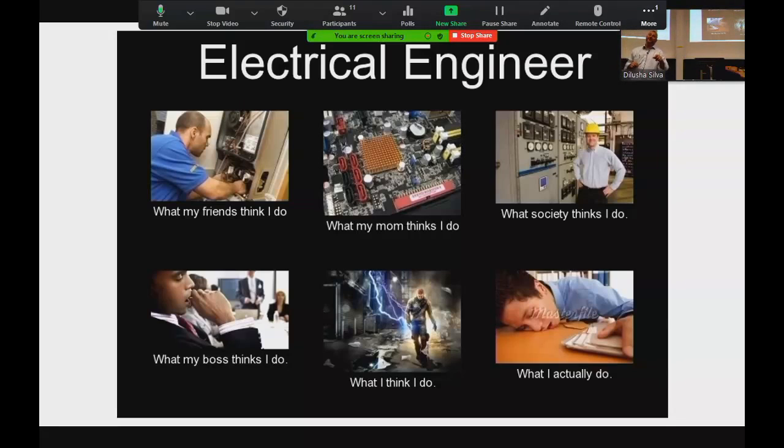Within this sort of application, for the load you're looking at, it would tend to be a mechanical device. We would look at a contactor that opens and closes. If you try to use solid state for these power devices, you'd struggle to find one that's rated for it. Your card reader will talk to a little PLC, and the PLC will have an output.